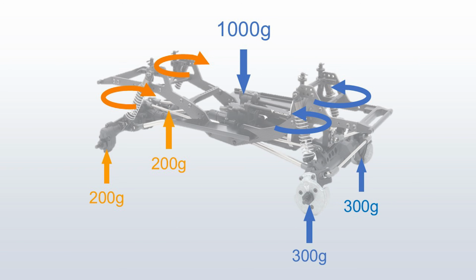You can contrast oil weight tuning with spring rate selection. I can tell you almost exactly what spring rate and preload to use based on your vehicle's weight, the weight distribution, and your target ride height. But oil weight is so much more complicated, it's better to be based on feel. There aren't simple formulas. You're going to fine-tune your oil weight based on wherever you are today and where you want to go. So when it comes to picking shock oil, ask around, get a starting point, and make changes based on your driving style and preferences.